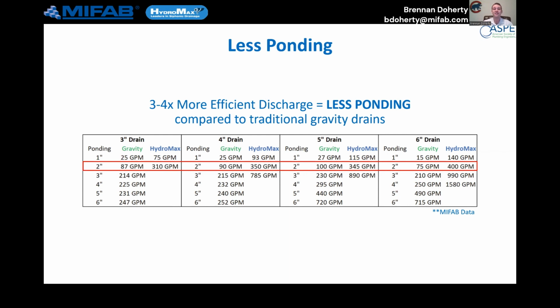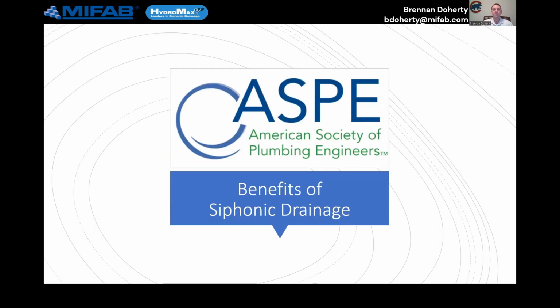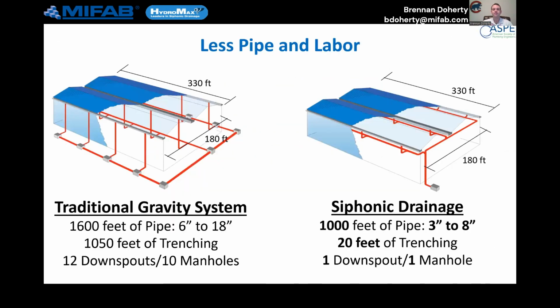If I have an architect that is educated, well, my roof drains can cover more square footage. So we can have less on that overall roof, less penetrations. Your trade-off in that instance, to be clear, is going to be insulation pitch. If we have 1 drain versus 2 drains, that's going to take more pitch to get it there. Now that we have our basic building blocks, let's put them together and see how it applies on real-life projects.